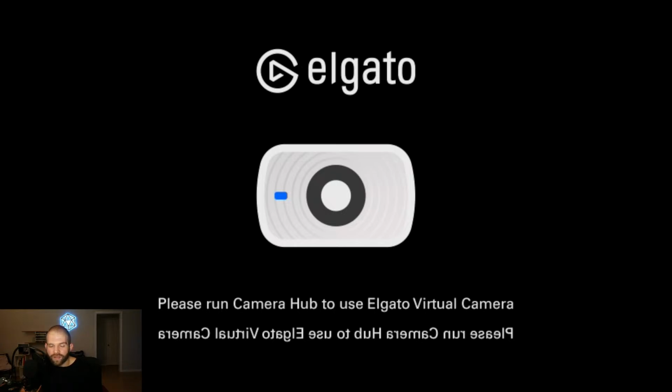So in order to not have it influence the image so much, we'd go back over here. And noise strength, we can set to 0.25 rather than 0.75. And we'll hit render again. Then I'll go straight to Dream Textures so that I can see the final result after producing the render and after applying Dream Textures over it. So we see it actually didn't change much at all. It basically just modified what the texture on the actual object looks like.